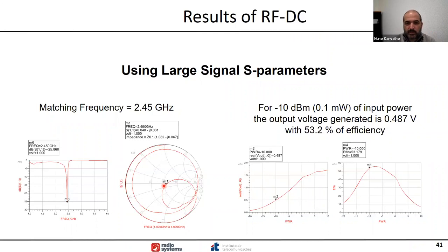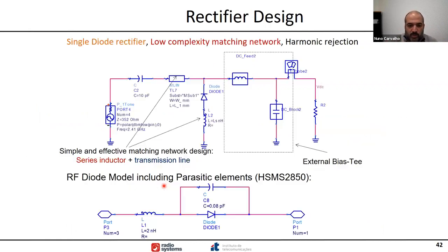We are working on that in my lab, but at this moment I will consider in this case a passive matching network using capacitors, inductors, transmission lines. So it's fixed. So we normally do an average between all these powers. And by doing that, we can optimize my input matching network.